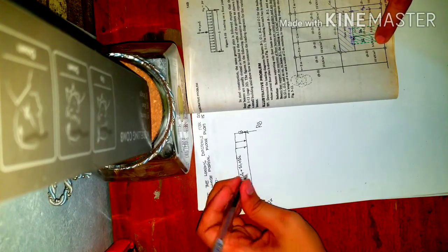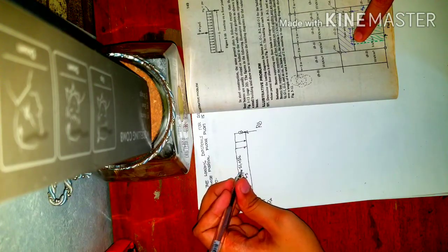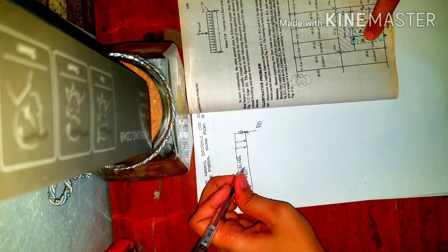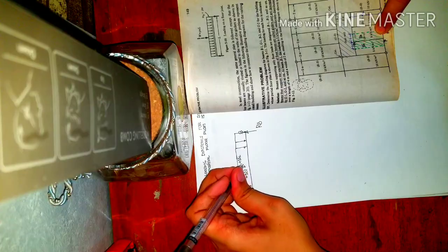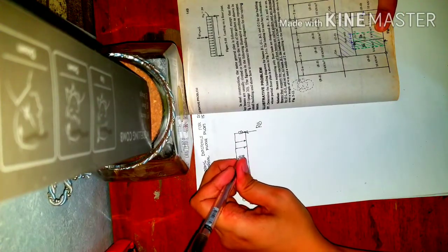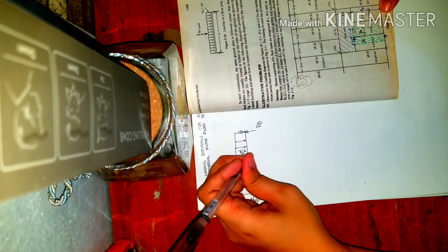So, ano ba yung omega 1? So, yun nga is yung 5 kilonewton per square meter multiply by 1 para maging kilonewton per meter. Okay? So, ito is yung para sa W1 and yung W2, pareho lang din naman. So, 5 multiplied by 1. So, the total uniform load na i-carry niyan is 10 kilonewton per meter with a span of 4 meter. Okay? So, from that, masosolve na natin yung reaction. And with the reaction, pwede ka mag-solve ng shear and moment diagram.